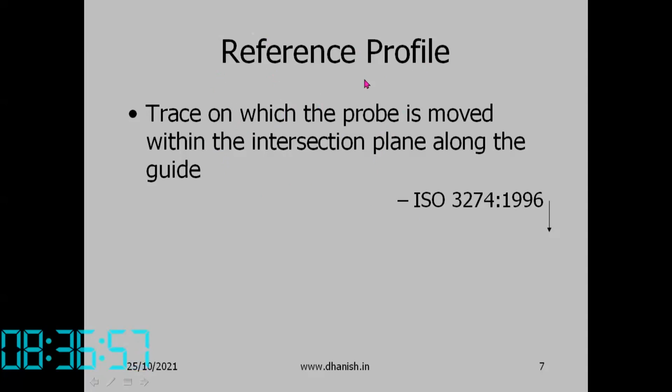If you are measuring a straight surface, usually it is a straight guide only. But in some applications, like when you want to measure the surface finish over a gear tip, you may have a guide which is of involute profile, etc. So this is the reference profile.